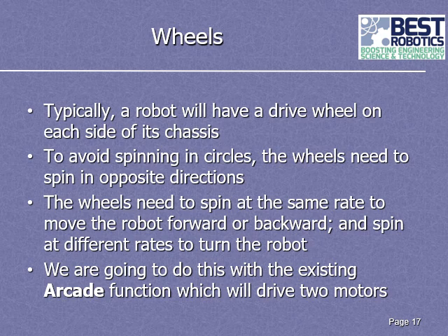This just leads us into the reasons why we're going to do the next function we're going to add. Obviously, most robots are going to need wheels. And we're going to be using something called arcade mode. And this is so that you can basically use a joystick in order to go forward and backward and left and right. And because the wheels need to turn in the same direction, even though the motors are pointed in different directions, that would mean that one motor technically has to move opposite the other wheel.